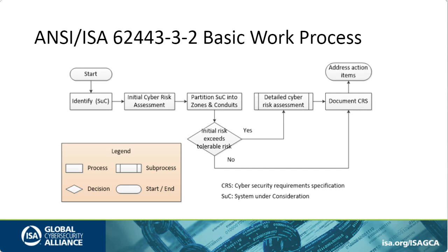Then you're expected to do an initial cyber risk assessment, followed by partitioning the system under consideration into zones and conduits, at which point you can ask the question, does my initial risk assessment exceed the tolerable risk? When you're doing the initial risk assessment, you're basically assuming that the likelihood is 1. You're simply looking at it from a consequence perspective, and if you're too high, then you would go on to perform a detailed cyber risk assessment.